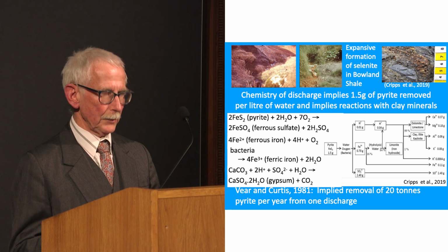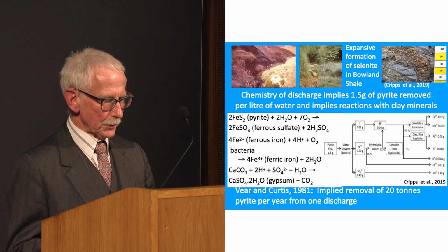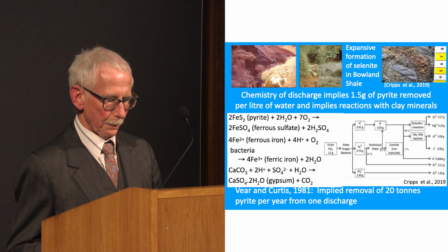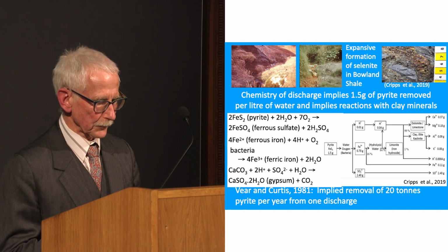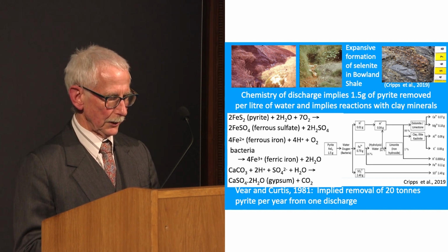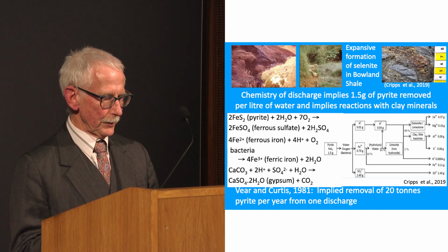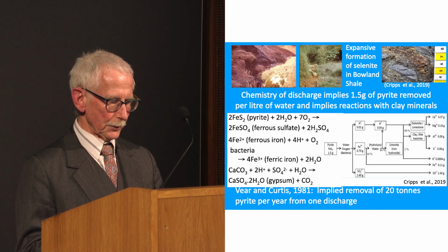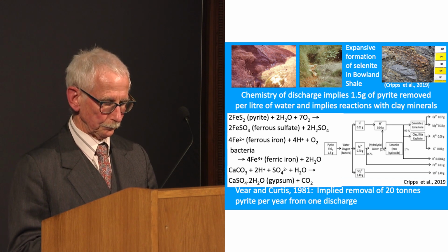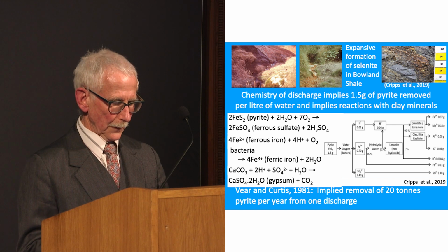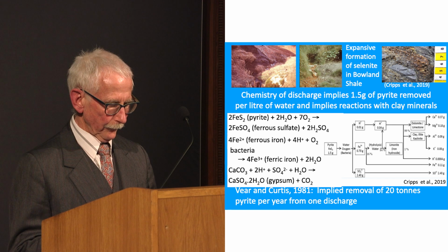Alwyn Veer, a student at Sheffield University, carried out studies of the chemistry of the streams and water seepages that occur on the landslide. These were acid and contained high levels of sulfate and metals, such as aluminium, magnesium, calcium, and potassium. And there were brown deposits of iron hydroxide in the watercourses, all of which pointed to solutions formed by the oxidation of pyrite. The reactions are shown on this slide in a simplified form.